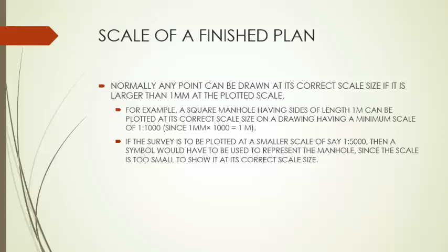If the survey is to be plotted at a smaller scale, let's say 1/5000, then a symbol would have to be used to represent the manhole, since the scale is too small to show it at its correct scale size.